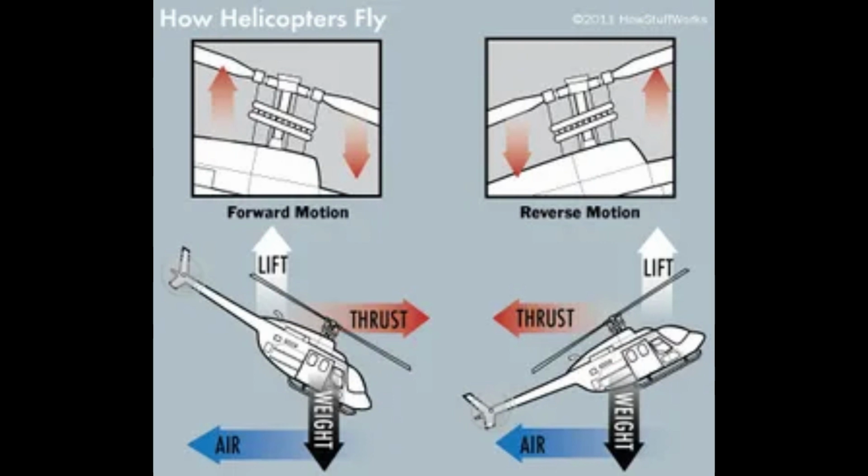Many helicopter accidents are caused from the rotor disc being overloaded. Simply put, pilots attempt maneuvers that require more lift than the rotor disc can produce or more power than the helicopter's power plant can provide. Trying to land with a nose-high attitude along with any other unfavorable condition, i.e., high gross weight or wind gusts, is most likely to end in disaster. The tail rotor also produces thrust. The amount of thrust is variable through the use of the anti-torque pedals and is used to control the helicopter's yaw.